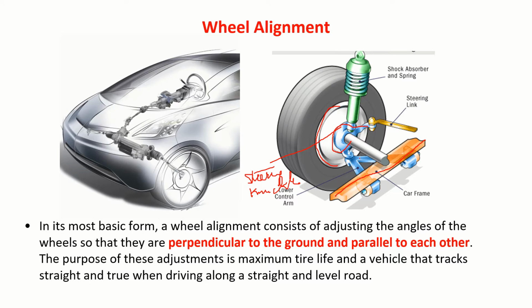So here I am using one suspension linkage that I call the lower control arm, and this one is a MacPherson strut. For understanding, let us call this the upper control arm. Then to the steering knuckle we have the steering link. Of course, this steering link will be connected to a rack and pinion arrangement. Then we'll have a steering column and steering wheel like this.